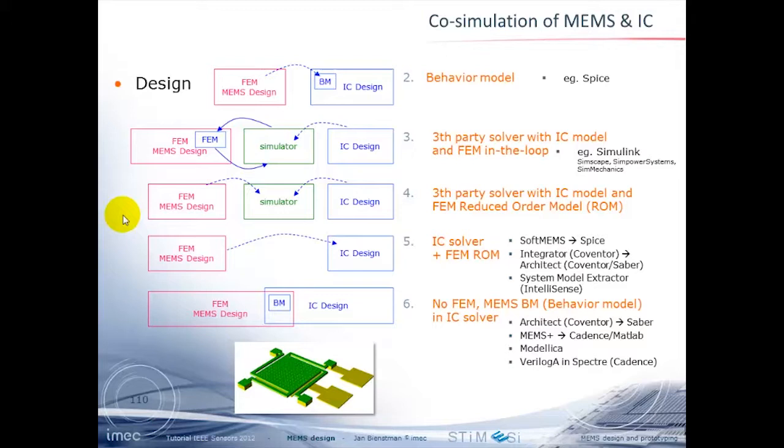And then you more and more overlap these two worlds. So I mentioned Architect, Coventor, which runs into Sabre. That was the old version. Now with MEMS Plus it runs into Cadence and MATLAB. And there are also some other tools that you can find on the internet, or Modelica, or, like I already told, some companies develop their own Verilog-A interface to do co-simulation of their electronics with their MEMS.